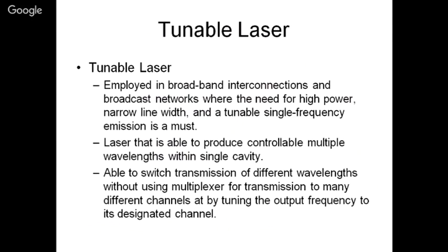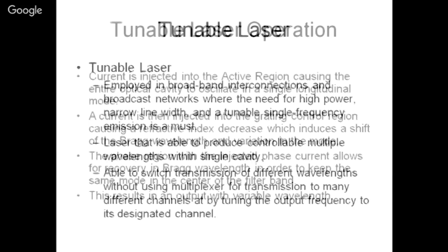There is a possibility of tuning the wavelength also. You can tune the wavelength just like you can select with the help of a grating. Different gratings, if you use, different light will be reflected. So you can also tune them for a single frequency, which we will be needing much more when I talk about wavelength division multiplexing tomorrow, because we are sending many wavelengths together. We have to combine them and then separate them. And the nearer they are, the more we can pack. So more will be the bandwidth of the total system. This tunability of laser is very important for wavelength division multiplexing and dense wavelength division multiplexing.